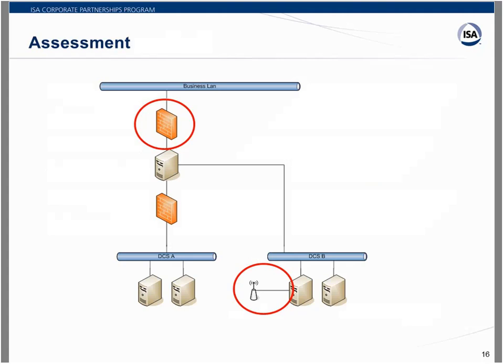Now, the mitigation of the risk of that may be as simple as a quarterly audit. The work order pops up and you say, I need to go check the settings on that unit, and it says, yep, it's still an SMS text device and it's not set up as a two-way cellular bridge, which it has the possibility of being. Another mitigation would be to buy something that could not be set up as a cellular bridge. But the idea is to identify where these risks are so that you can decide how much effort you want to spend minimizing them.